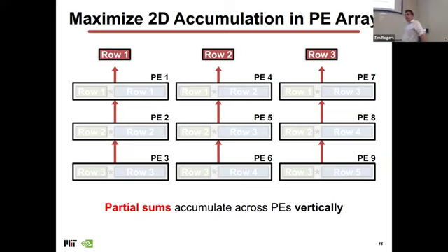So the mapping here gets more difficult. The mapping in a weight stationary architecture is pretty straightforward. You just dump the weights onto each processing element in the register file, and then you stream things through. Here, I need to make some decisions, and I'm going to have a fixed size PE array, but all of my network sizes are going to be different. So I need some kind of scheduling mechanism that will take any arbitrary convolution or any arbitrary fully connected network and then map it onto this mix of processing elements in this row-centric way.